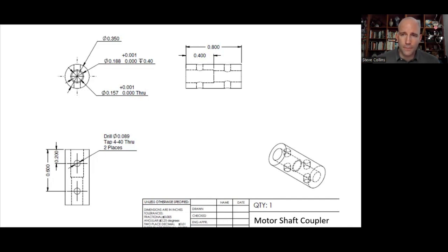All right, you got a guess? Yeah, probably we would manufacture this out of a steel because the component is pretty small. It has these complex features like threaded holes, and it experiences pretty high load. I mean, this is going to experience the full torque of the motor, and it's at a critical point in the transmission. So that high density of the steel doesn't hurt us too much, but the high strength of the steel is a real asset. And we might make this out of 302 stainless steel or something.